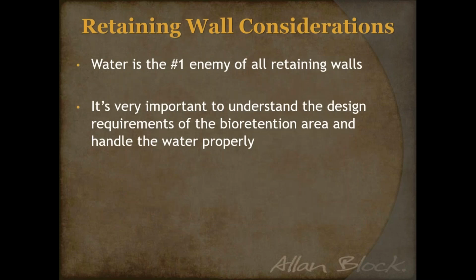I mean, everything we do, there probably isn't a retaining wall course that we offer where we don't talk about water management. And depending on which expert you talk to, I've heard people say that most of your failures are because of water. So it might be 90% or even as low as 70%. It all depends. But we just know the vast majority of problems associated with retaining walls are because people are not handling the water properly. And that just compounds when you know you're going to have a bioretention area. So let's get into this a little bit.